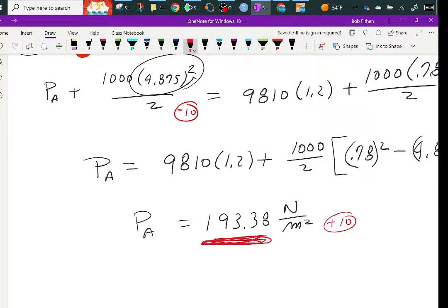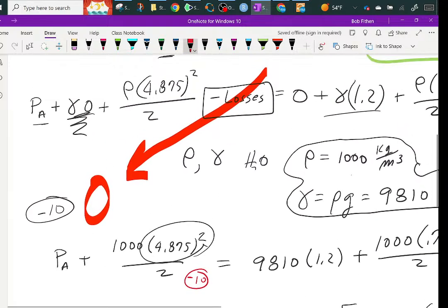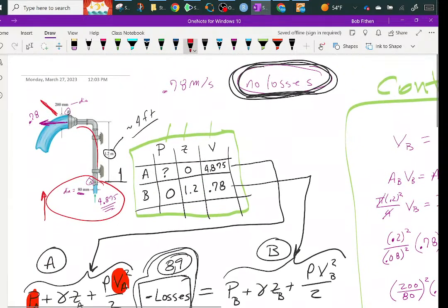If that's the lower limit, then if you're going to be using a pump and you tune it to getting 193, don't expect that flow rate to be met coming out here. It's going to be significantly lower than it would be if you're ignoring those losses. But if it was a real short pipe and really big diameter, it'd be fine. You know, ignoring those would be fine.